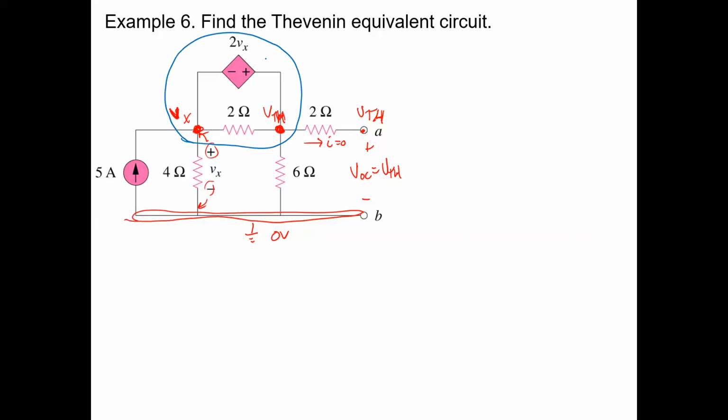Well, there's a voltage source. Is it any old voltage source? A dependent voltage source, but that doesn't necessarily make it a supernode. What makes it a supernode? It's floating. What does floating mean, Isaac? It's in between 2 nodes.